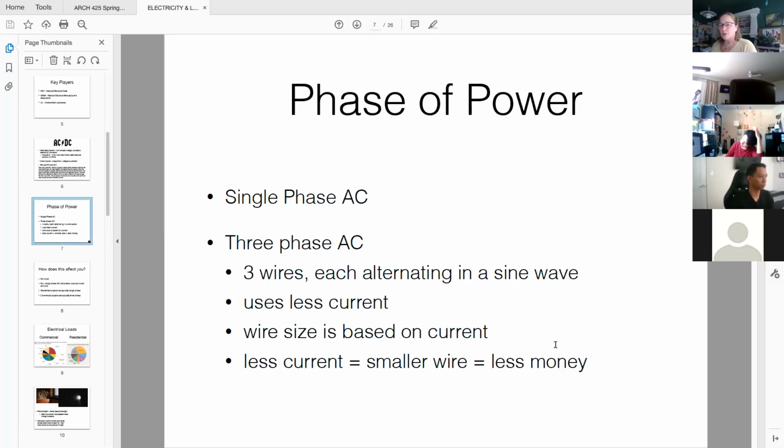However, once you start getting into much larger buildings and you want to have much larger equipment, instead of putting in 4 5-ton units, you're going to want to put in 1 20-ton unit, because then you're only buying 1 piece of equipment, and that's going to be a lot more economical than 4 pieces of equipment, and usually less square footage, which is going to keep your footprint size down, which is going to keep your overall building cost down. So just be aware that there is a difference from residential to commercial.